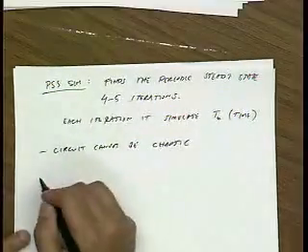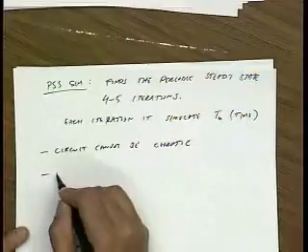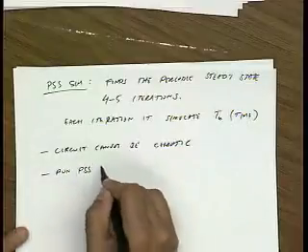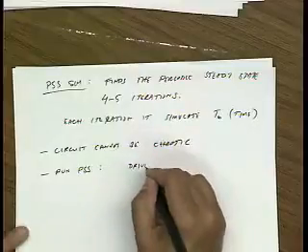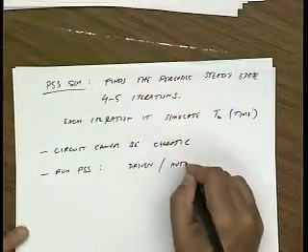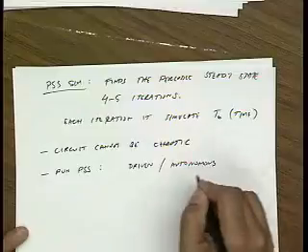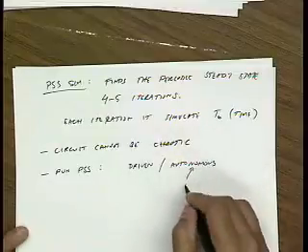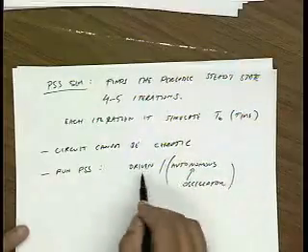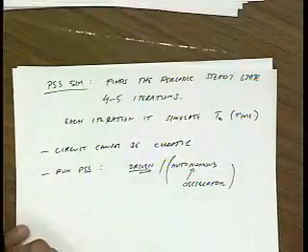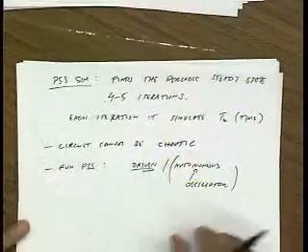And then the other thing that you need to know when you run PSS, what parameters do you give it? First, you have to tell it, is this circuit a driven circuit or an autonomous circuit? Okay? Autonomous circuit is something like an oscillator. For now, we're talking about mixers, they're driven circuits. Okay? So we'll talk about autonomous circuits later.